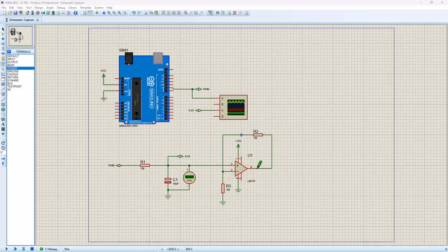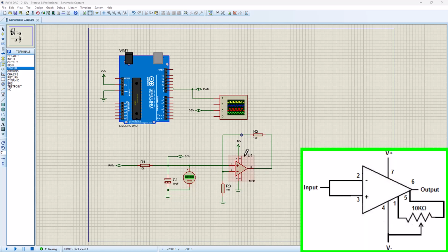It's going to have some voltage already there. Now, if you want that voltage to be zero when there is no input voltage, you basically need to connect a potentiometer. That will be connected across pin 5 and pin 1, and then the output of the potentiometer must be connected to your negative pins here. That way you can adjust that voltage output to be 0 volt.